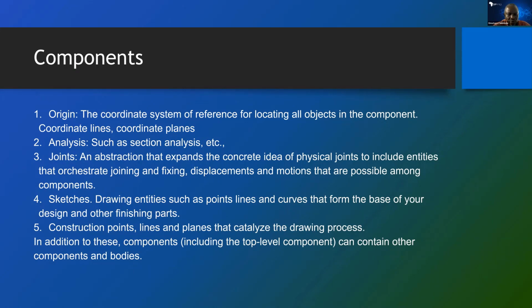And you can choose. For instance, if you need a plane, you can go to the origin to select any of the coordinate planes. You may be able to select other planes from other methods, but those are always available inside your component. Once your component is defined, there are at least 3 planes that you have available to you in case you need to perform a function that requires a plane.